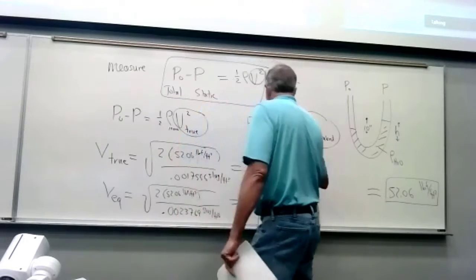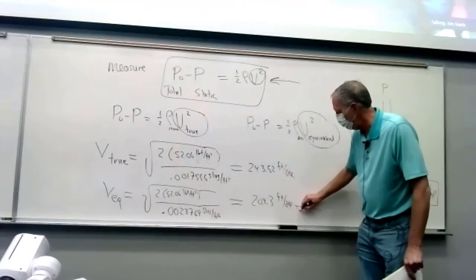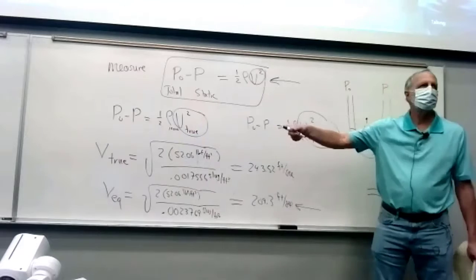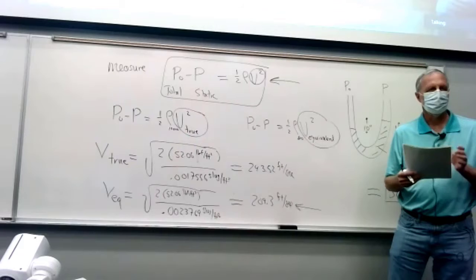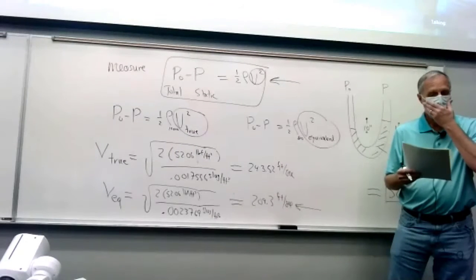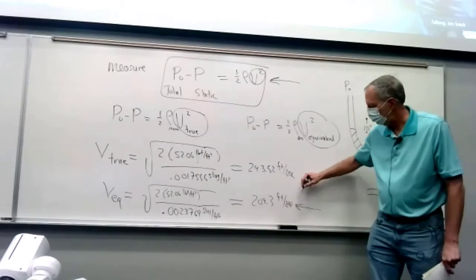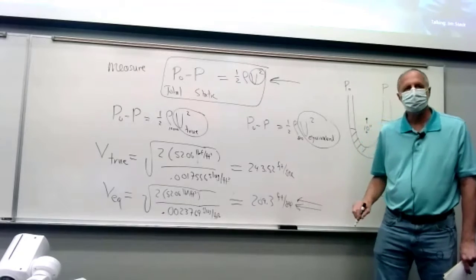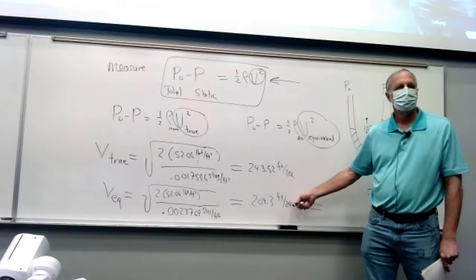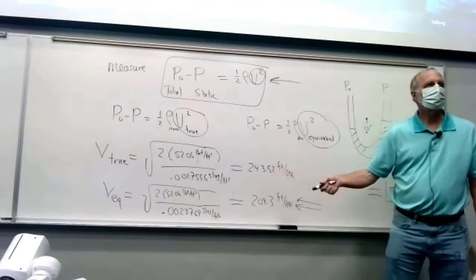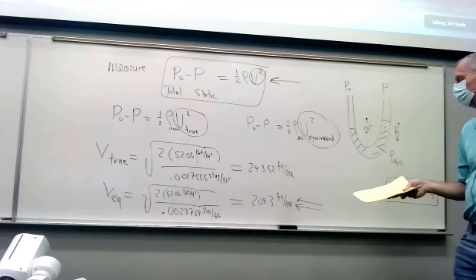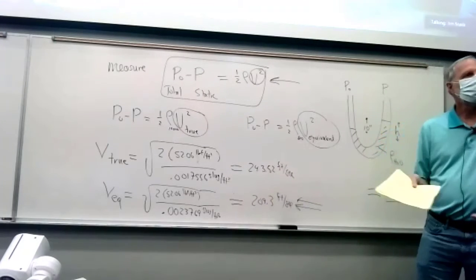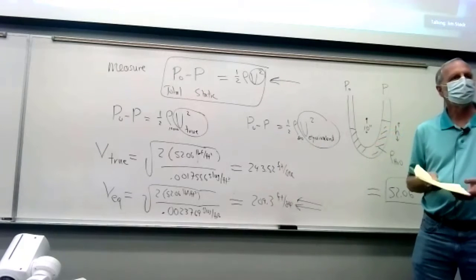So this is the true airspeed. This is the equivalent airspeed if we sense that pressure difference at sea level. Well, it turns out that on a lot of airplanes that have airspeed measured with a pitot-static tube, this is what you see. You get the equivalent airspeed because there's no way for it to know the density of the air outside. And so then as a pilot, you have to remember that this is reading low to what your actual airspeed is, or you have a chart that converts for you.